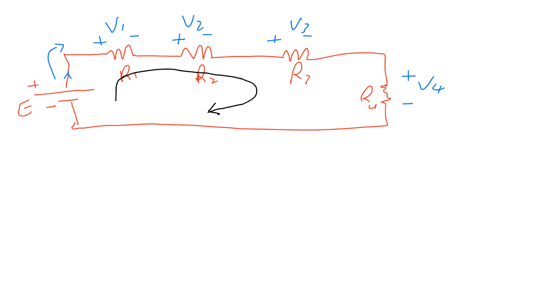So the clockwise direction. So this is your assumption. Then trace the current. Let's start from this point here, which is the source. I will start from one point and I will get back to the same point. So the current here, the I here, as clockwise direction. This is number one. So number one here, clockwise direction.